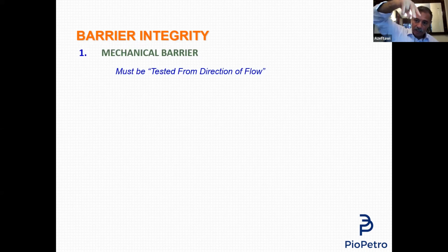But one time while crossing at the middle, the ladder will break. Because when we designed the ladder, we didn't take into consideration this force that comes from this direction. The stress analysis we did doesn't include this. So please do use the equipment for the purpose it is designed for.